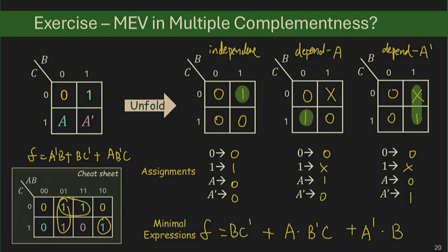Again, in this case, it doesn't make much sense to go through this MEV method because you can represent the three variable function directly. You typically only use it if you are looking to represent more variables, like more than 4 variables in a 4 variable K-map. Right? But I think as an illustrative example, this one serves the purpose. All right. And that's everything about MEV.